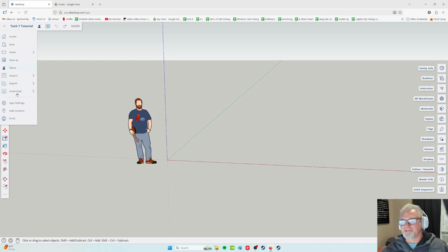So we will use that especially to import something or download. And if you're curious how you 3D print things, some of you are curious, after you create something, you go here, and then to the download as an STL, I think it's stereolithography or something like that. That's the type of file that a 3D printer can read. So anything you make here, if it's done correctly, you can download it as an STL and then send it to a 3D printer, and it will print it.